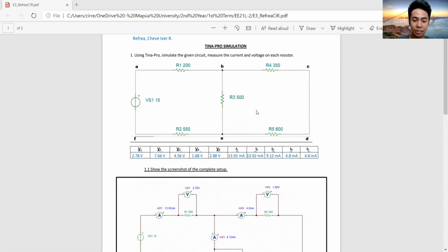First off is Kirchhoff's current law. Kirchhoff's current law, or KCL, is the first law that deals with the conservation of charge entering and leaving a junction. To determine the magnitude of the electrical current flowing around an electrical or electronic circuit, we need certain laws or rules that allow us to write these currents in the form of an equation. These network equations are those according to Kirchhoff's laws, and as we are dealing with circuit currents, we will be looking at Kirchhoff's current law, or KCL.